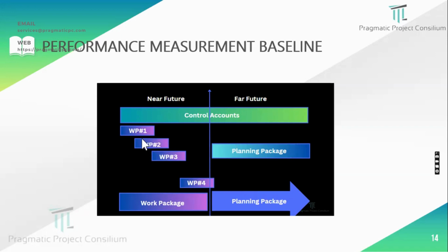While executing work progress 1, 2 and 3, as we are nearing 4, only at the end of work progress number 4 do we come to know what the next 3 weeks to look at are, what things we are closely monitoring, like a 3 weeks look ahead, 5 weeks look ahead. That way we monitor the progress and move the planning packages into work packages.